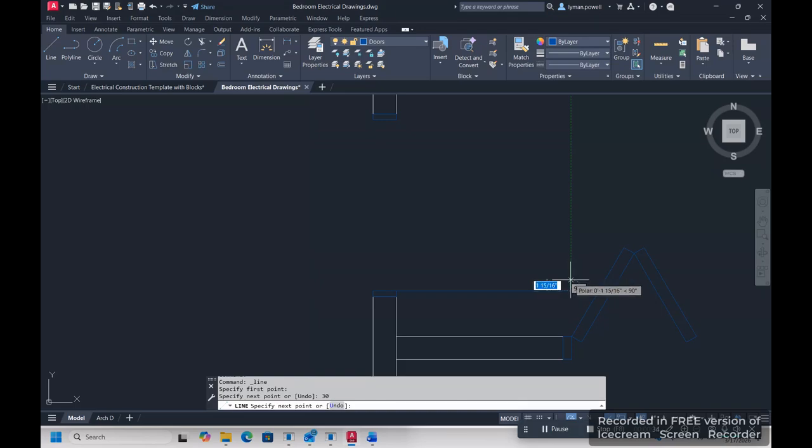And then we're going to escape again, and I'm going to do an offset. You could go ahead and finish it. I just want to get you kind of used to using the offsets. I'm going to make our door 2 inches thick. So I'm going to hit 2, and then I'm going to add it 2 inches thick. And then we'll add our lines on the inside there.